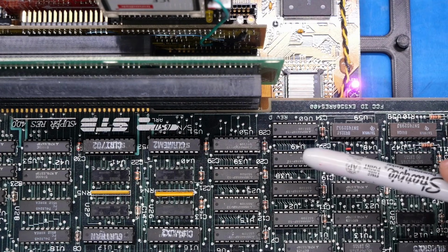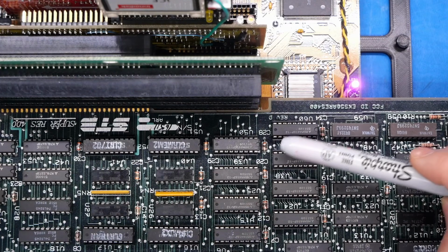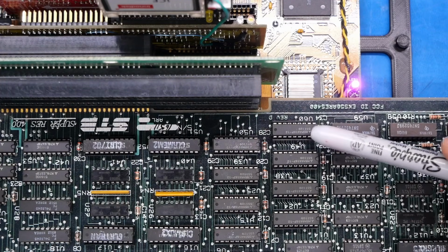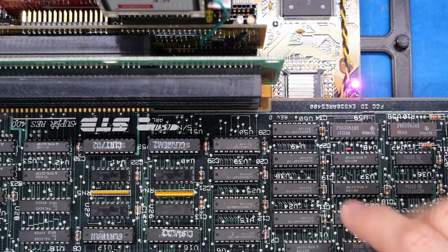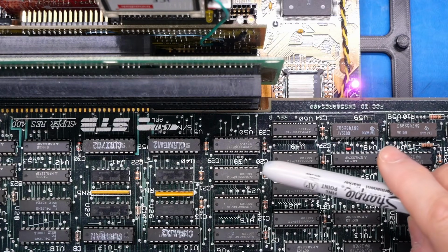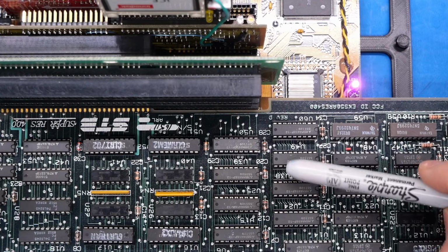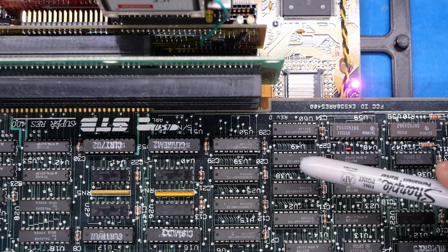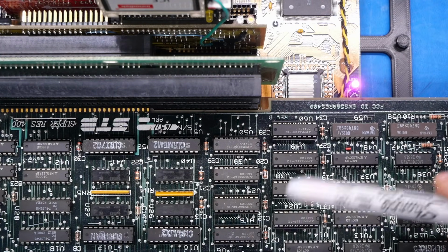But because this has 64K, we know these extra chips are used for the higher res modes, and CheckIt is only going to really look at 2 of these chips. But you really have to imagine that all the text modes and the CGA graphics mode and the RAM check in CheckIt, all of that activity is happening out of the same 2 chips. And there's a few ways we could go about trying to figure that out. Well, one is these are in sockets. We could just take out all the chips and then start putting chips back on the board until we start getting a functional CGA mode. Then we'll know that those are the two chips that are relevant, and the rest here aren't being used, except for the higher res modes.